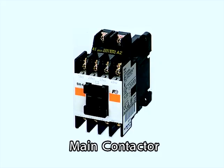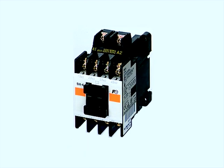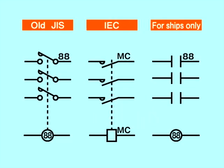The main contactor is used to turn on or off heavy load current supplied to the motor or heater. The main contactor's structure is similar to that of the control relay. It turns on when a current is passed through the built-in coil. An auxiliary relay similar to a small control relay is attached to it, and it is interlocked with the operation of the main contactor. In many cases, it is abbreviated as MC in the circuit diagram. The figure 88 is the control device number for the MC.